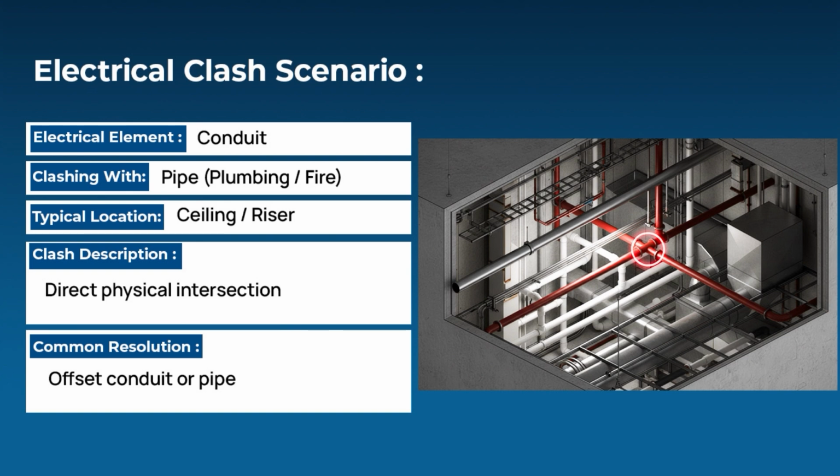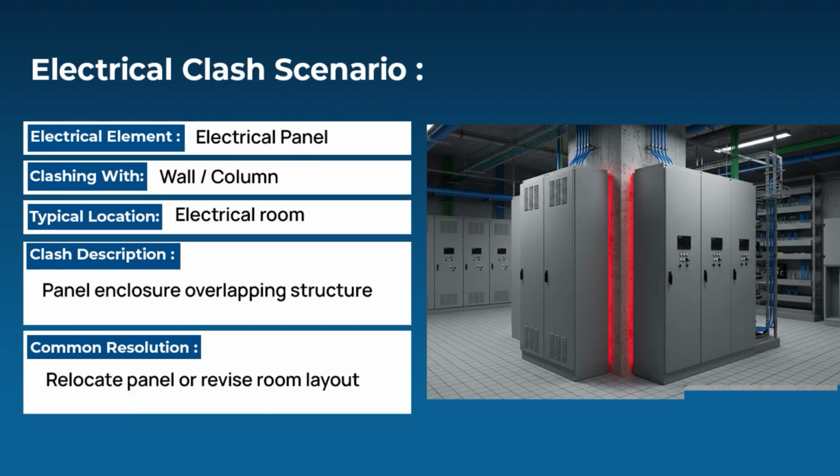The electrical panels here, where a panel will be difficult to locate or resize. These can be resolved using the relocation of the panels, and cable trays with the sprinklers and the panel door adjustments. All these are considered as hard clashes. As we discussed before, the adjustments of the lightings where light fixtures come in above the ceilings. As you can see here, it looks like this: soft clashes.